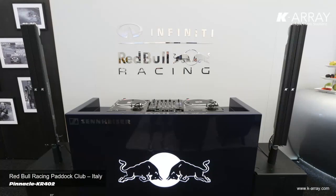You decrease the throw of the beam, because it's a shorter array, right? But at the same time, since you have 2 columns mounted, you double the SPL. So in this case, they didn't have to cover a long room, so they decided for this Red Bull event to go with 2 columns side by side to increase the SPL and reduce the throw of the array.